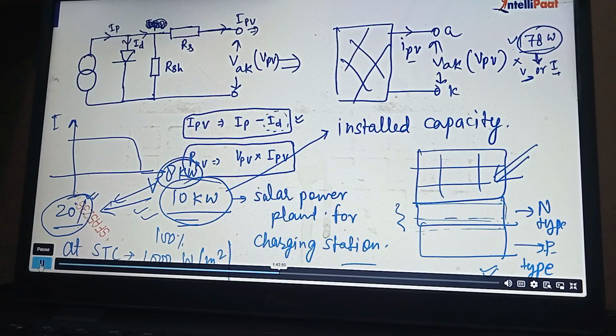Right. So as soon as we have these holes and electrons in N-type and P-type material, they are going to recombine at this stage. At this, we have some holes like this, which are recombining with the electrons. And at the same time, we have some free electrons as well, which will cross this depletion region, because you will send some energy through this. So some free electrons, they will go to here.